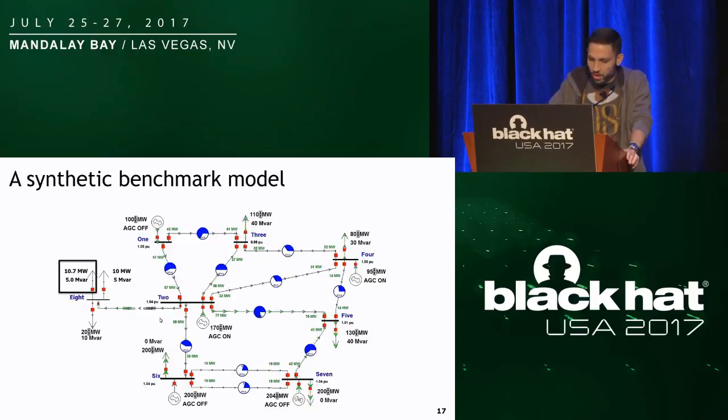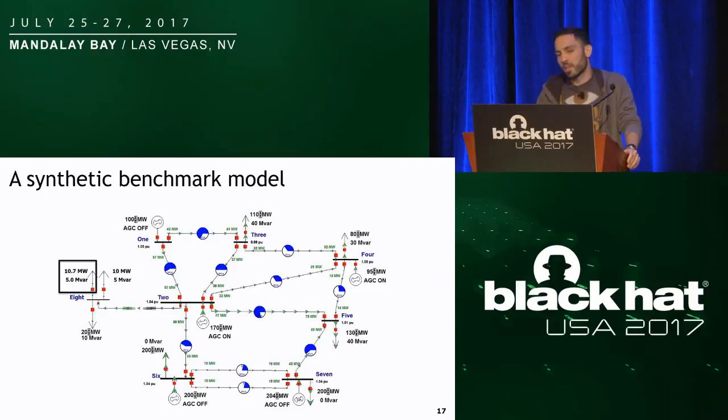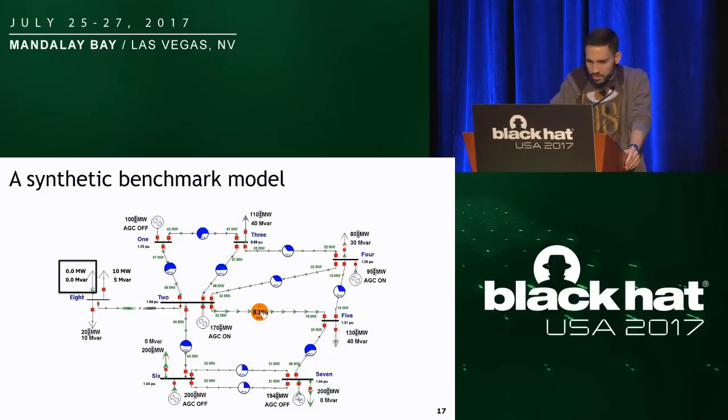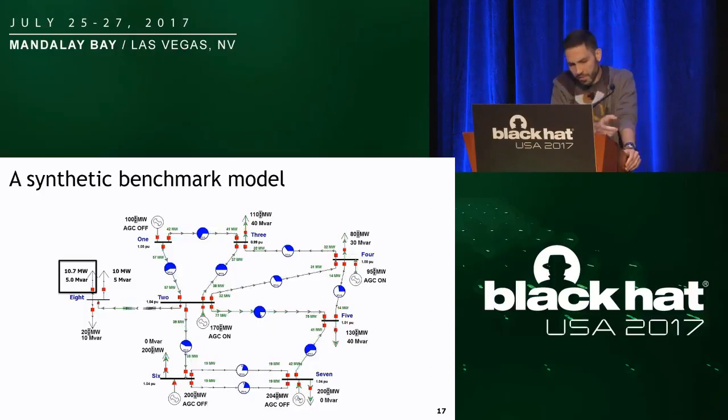What we have here is actually a PowerWorld simulation of a synthetic power system. PowerWorld is a power system simulation package that has all the necessary tools to perform tasks like optimal power flow, contingency analysis, fault and sensitivity analysis, etc. The green arrows you can see here are power flows, and we have configured one of the switches in this PowerWorld model to be controlled by our hardware. Specifically, the switch is a 10.7 megawatt load on bus 8.